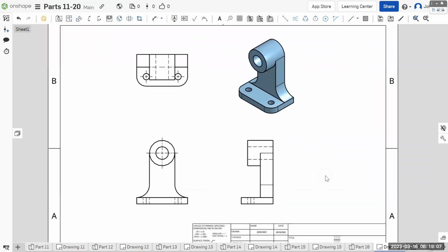Okay, so let's do some center marks. Things look curved. We've already got center marks for these holes. We need a center mark for the outside of that, center marks for here. And that's every curved surface on this view. The curved surfaces, we already have a center mark for there. The only other curved surfaces are there. Okay, and let's do our through lines.